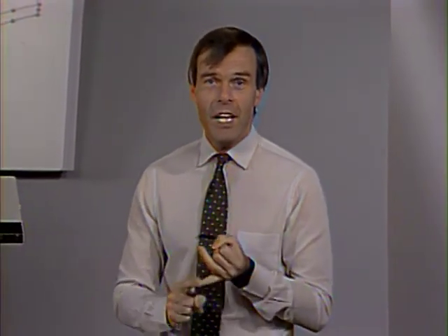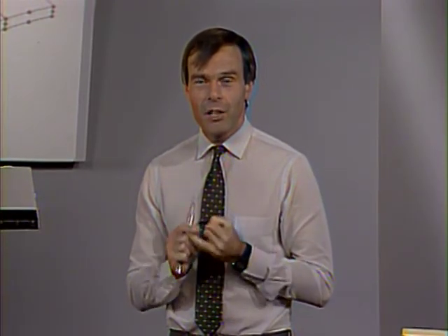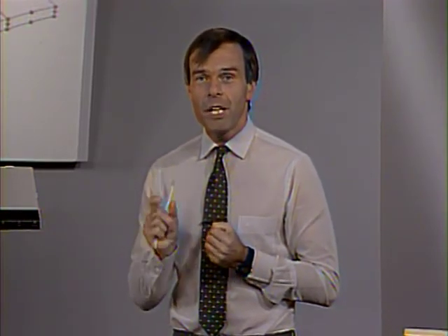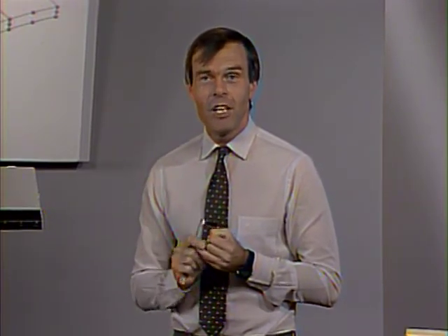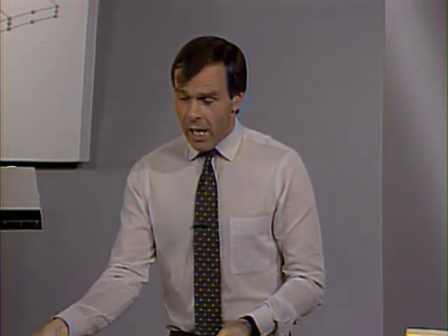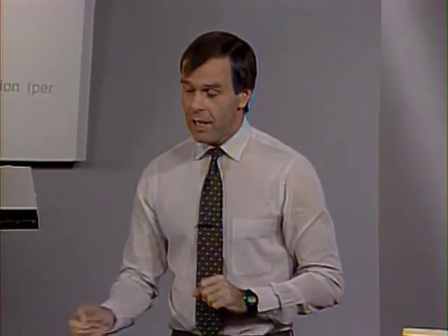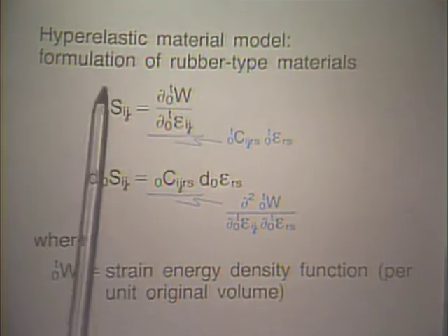This completes the first large item that I wanted to talk to you about, namely the use of constant material moduli, E, nu, E_A, E_B, etc., in large displacement, large rotation analysis, but small strain analysis. We found that the applicability of these constant material moduli to large strain analysis is really very questionable. For large strain analysis, we use frequently a hyperelastic material model. And that is very widely used to analyze rubber materials.